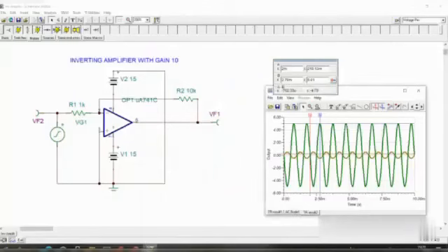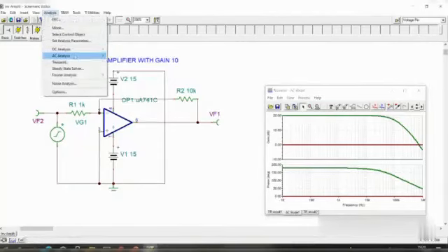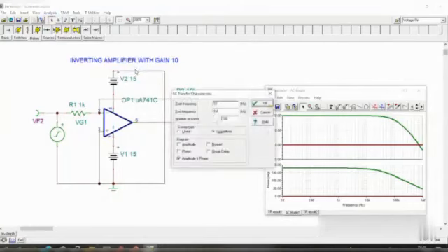So in that, you can see that for the AC Bode, here already we have placed AC Bode. You can see this one is from 10 to 1 meg, because I have selected like that. If I am putting again another AC analysis and AC transfer characteristics, and if I am putting say 1 kilohertz from 1K, 1 kilohertz means it is 1000 hertz.